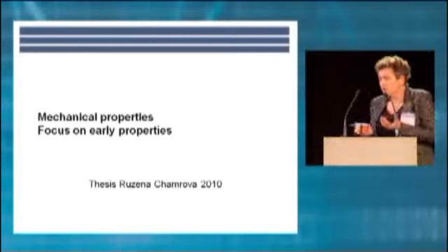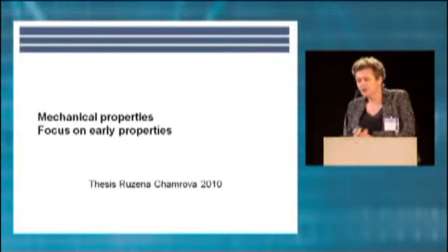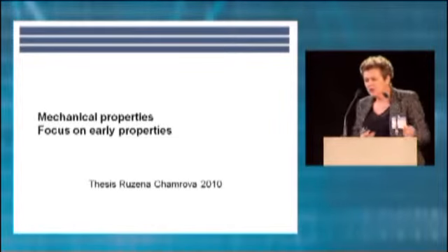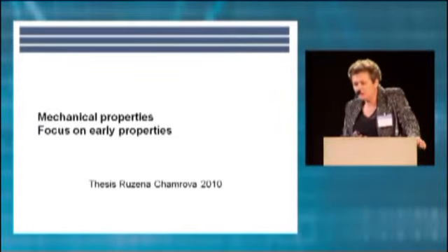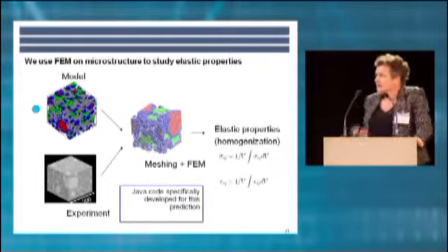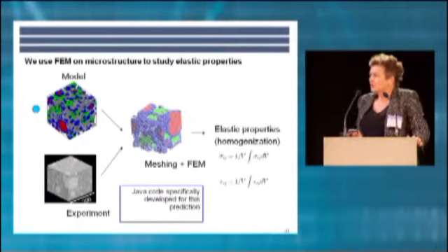We, of course, want to go on and look at mechanical properties, and particularly we're interested in how these properties develop during the hydration process. It's comparatively easy to capture the effect on final properties, but from a practical point of view, we want to know how fast strength develops, when we can demold the concrete, etc. And here we bring in different mathematical methods.